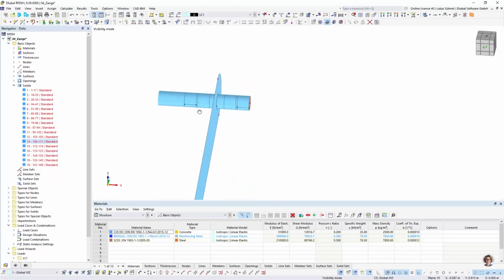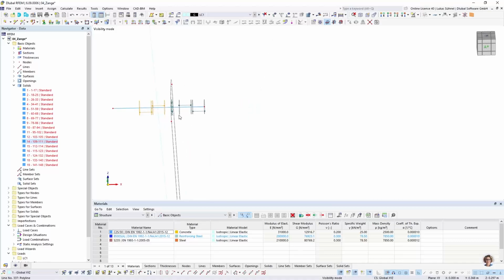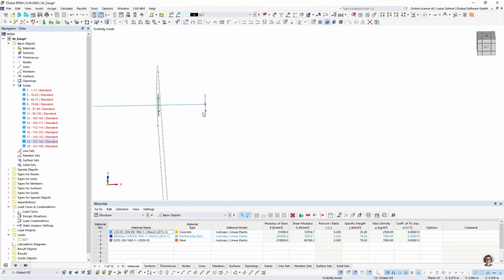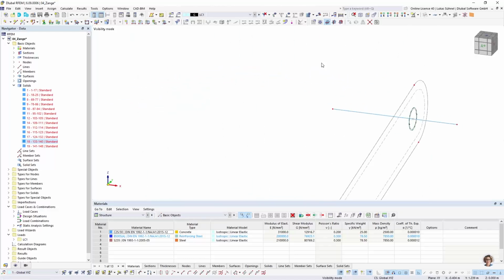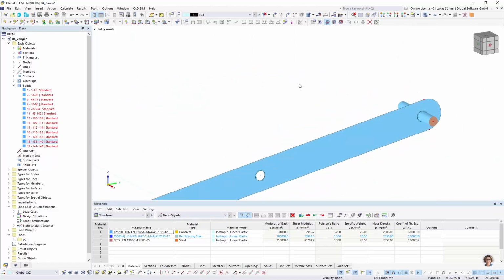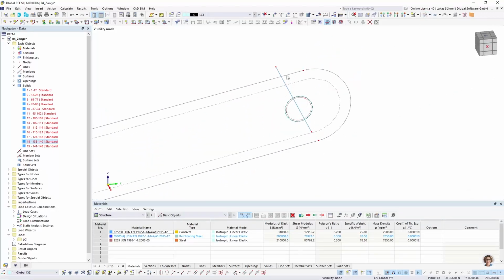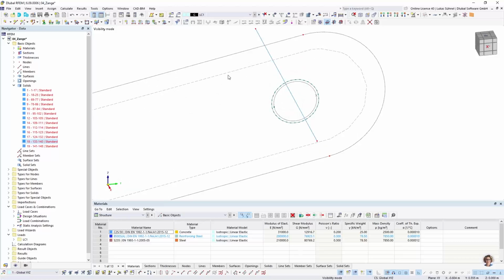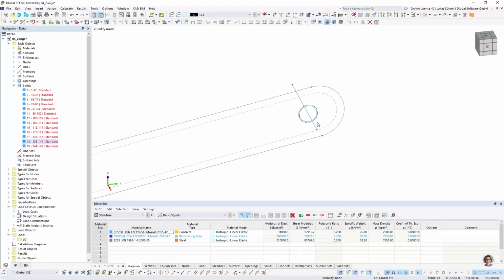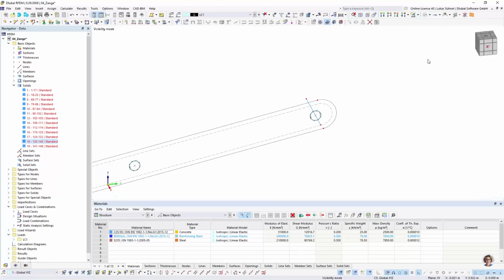with its boundary lines. And then we can change the rendering. There are some lines remaining. I can simply delete them. And I have my simplified surface and beam structure. And concerning the connection between this bolt and this metal sheet, I would use maybe like a wheel of members or beams, or coupling members, to create a proper force transfer. Yeah, this would be my simplified approach for that model.